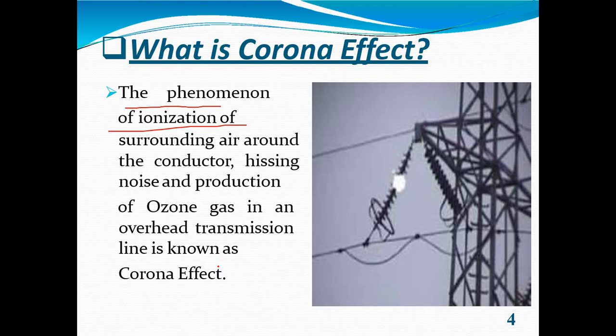If conductors are polished and smooth, the corona glow will be uniform throughout the length of the conductor. Otherwise, rough points will appear brighter. With the DC voltage, there is a difference in the appearance of the two wires. The positive wire has a uniform glow about the corona and the negative conductor has a spotty glow.